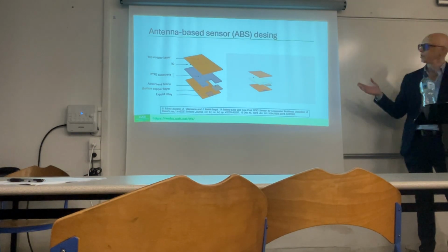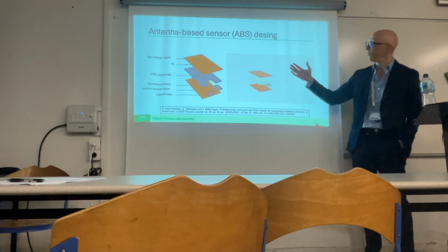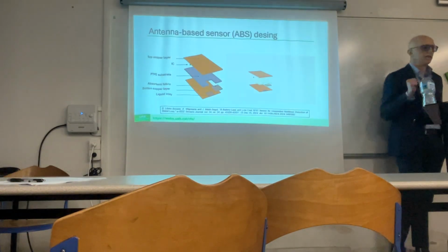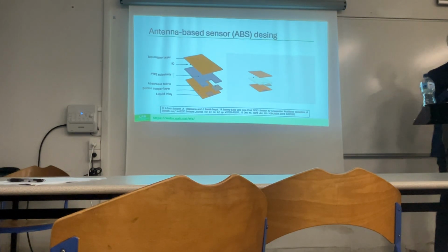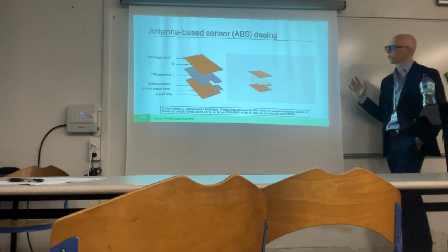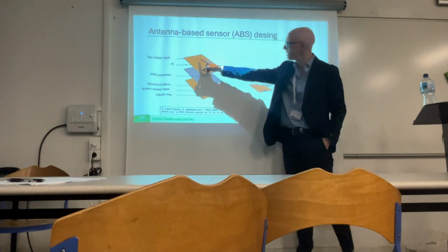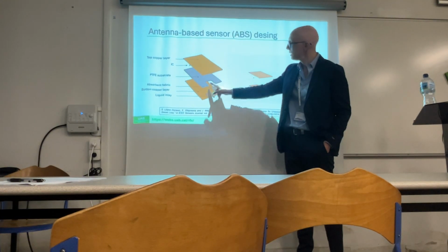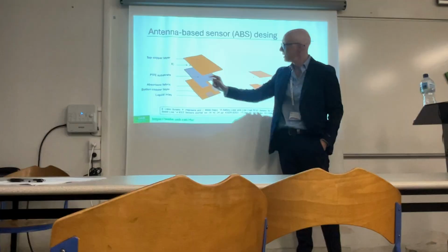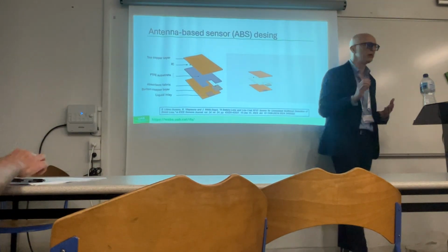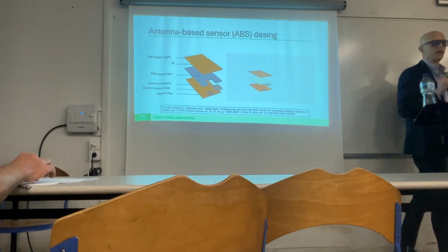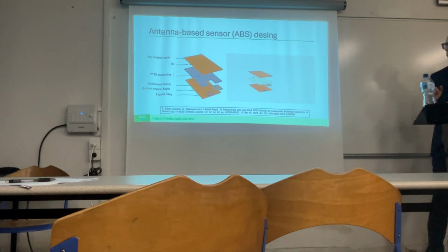This is the 3D exploded view of our antenna design. It consists of a short-ended patch antenna, and this is the top layer, short-ended to the bottom layer, and the antenna is mounted on a thin Teflon substrate of 1 millimeter.